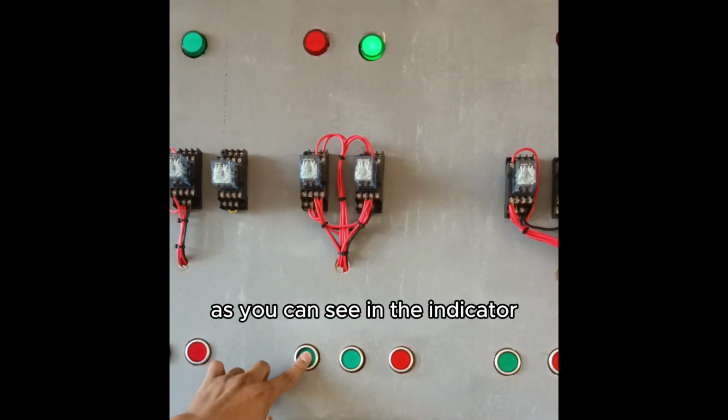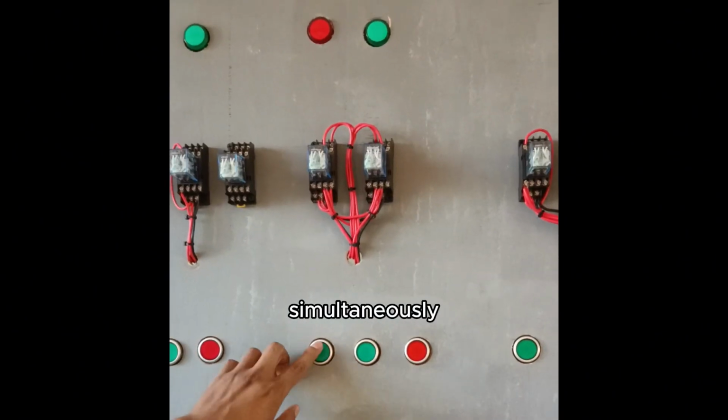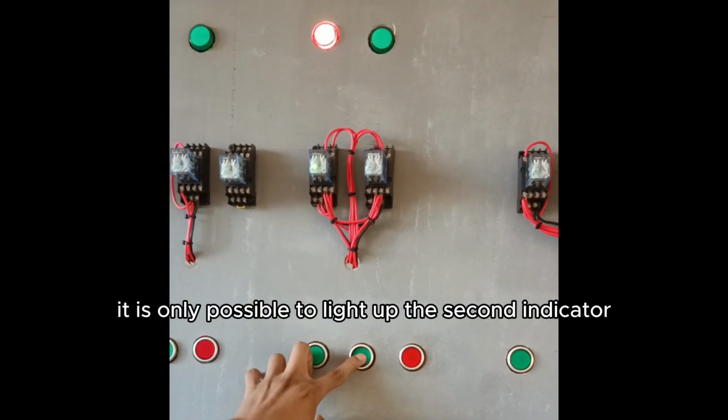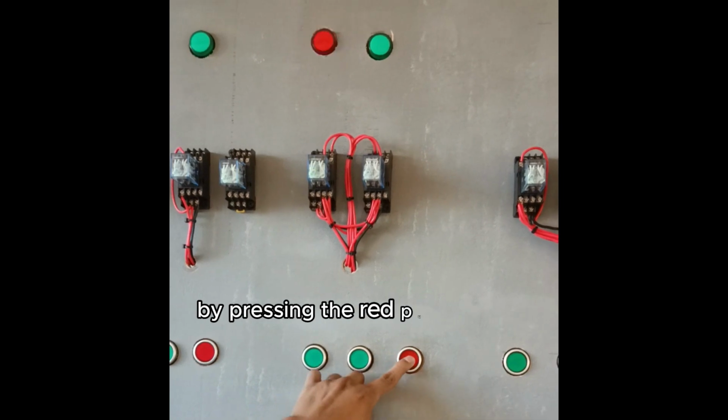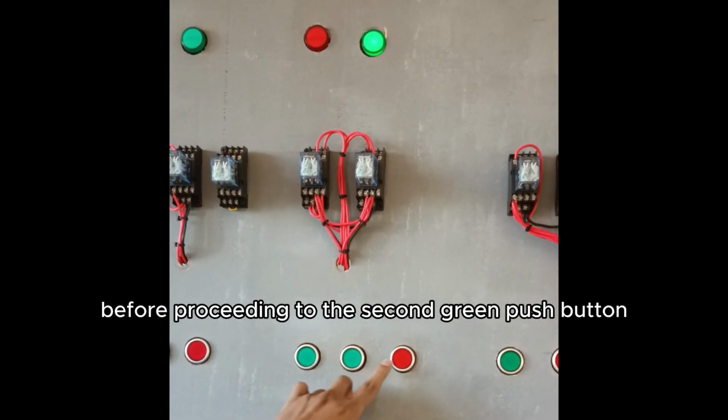As you can see in the indicator, you cannot press the two green push buttons simultaneously since the second indicator does not light up. It is only possible to light up the second indicator by pressing the red push button first, before proceeding to the second green push button. This also works vice versa.